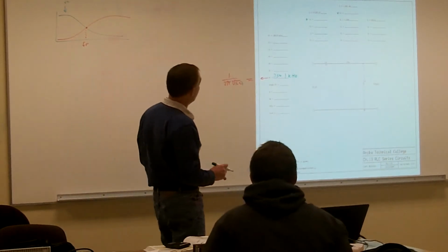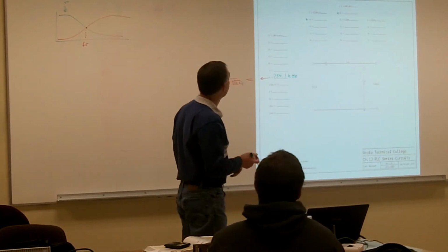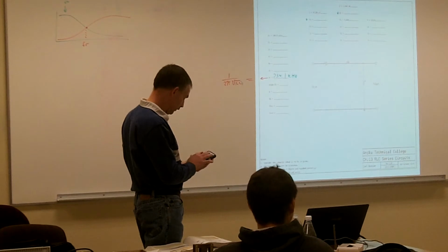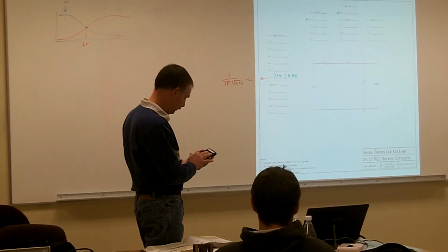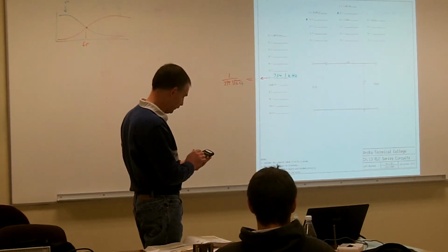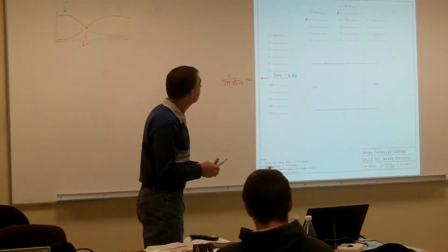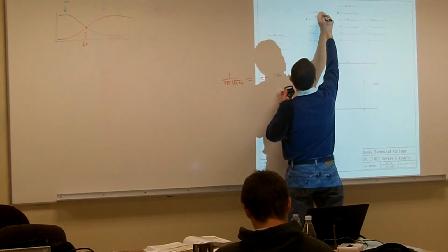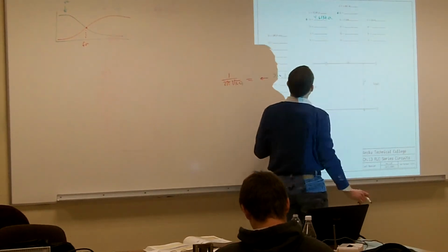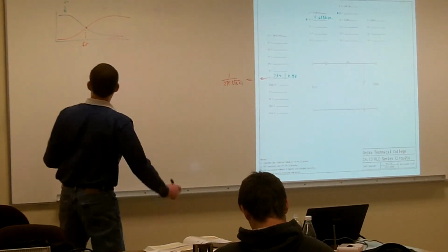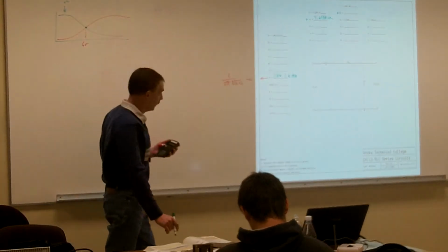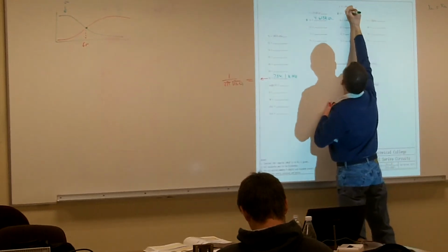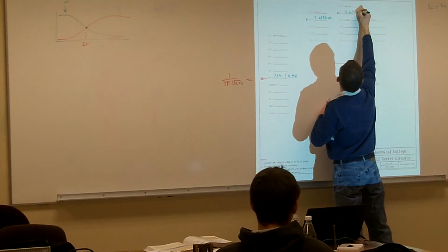All right, so what do we end up for X of C? Okay, so you got 4.613 kiloohms. Okay, and then what do you get for X of L? Same thing. We said that right here, that X of L and X of C are going to equal. So we know that at my resonating frequency, X of L is going to equal X of C. So then we should get the same thing. 4.613.